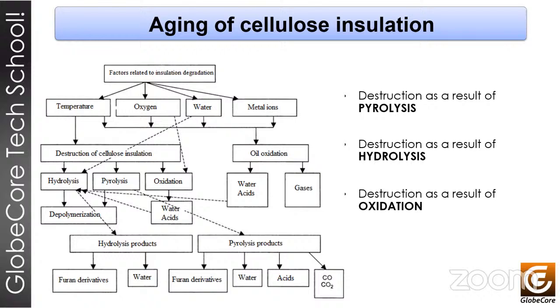As for the measurement of relative oil humidity, it is carried out with a thin film capacitive sensor, which allows continuous measurement during transformer functioning. Measuring the oxygen content in the oil during transformer functioning is difficult due to the high cost of the instrument to monitor gases dissolved in oil continuously.